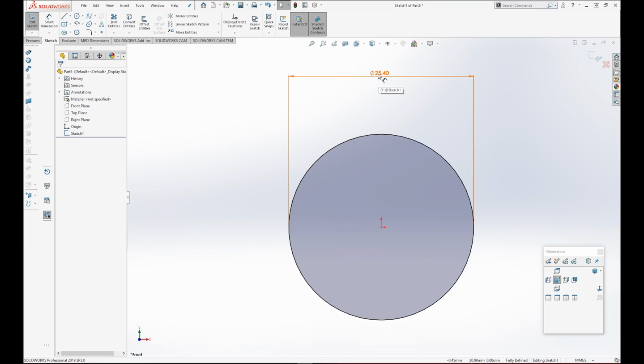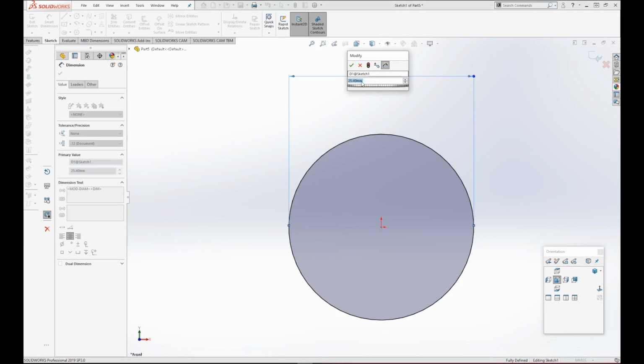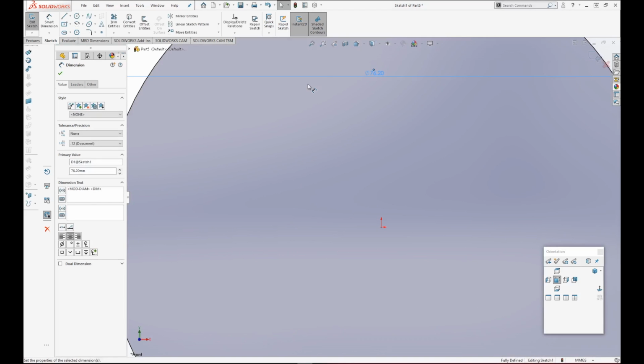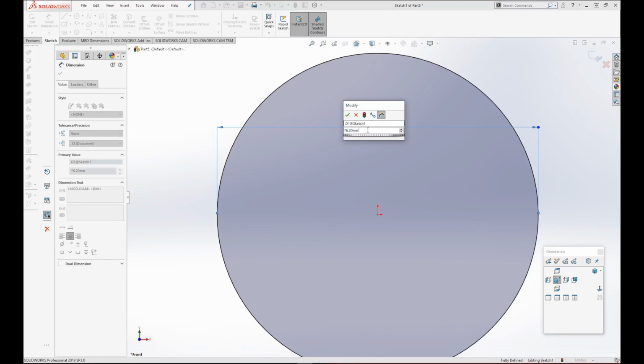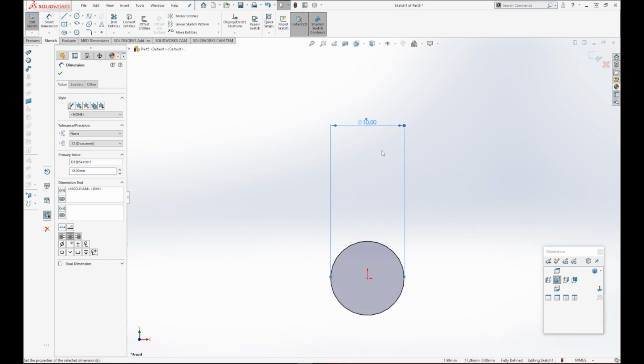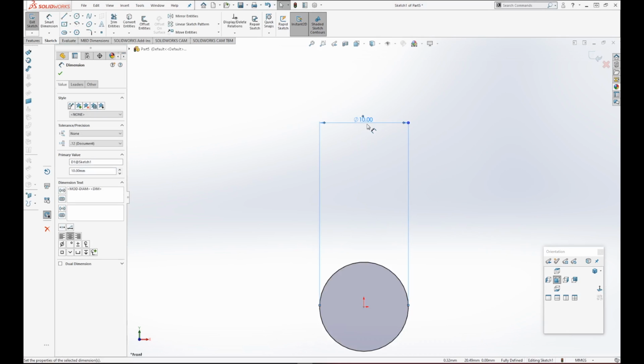If you find yourself changing from millimeters to inches, you can actually just work with both, and all you have to do is change the last two letters. So IN would be working with inches, and then MM will be working with millimeters. Since we changed it from inches to millimeters, it will default and always show millimeters, but you can obviously always use inches by typing in that IN at the very end of your number. So I'm going to go ahead and change our circle here to 10 millimeters.